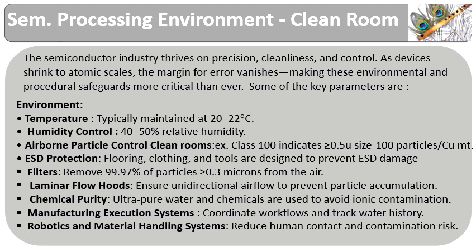Following are some of the clean room features employed in the semiconductor device manufacturing environment. For ensuring process stability, clean room temperature is tightly regulated between 20 to 22 degrees Celsius. To prevent static charge buildup that leads to material degradation, the humidity is maintained at 40 to 50% RH.